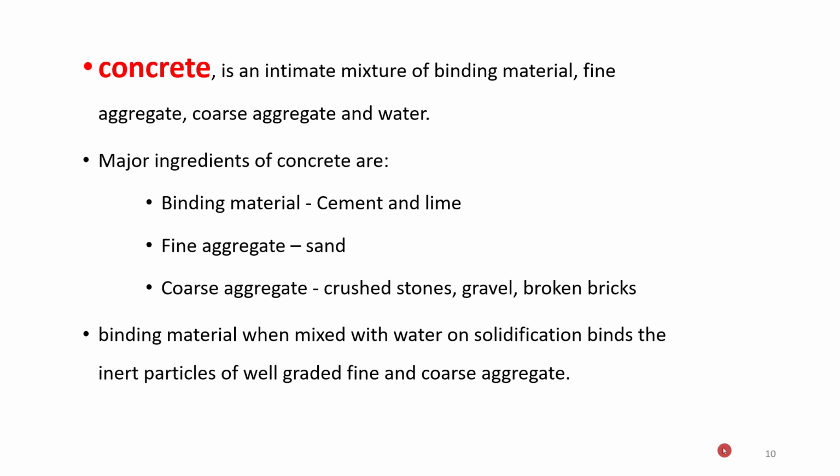When you come to the concrete, I'm explaining only the topics which I haven't taken in the class. I covered the major portions, and these are some additional topics in concrete. So you all know how to make a concrete. The concrete is basically the cement mortar plus an extra additive, the coarse aggregate or the metal. So when you mix the concrete, compared to the cement mortar, you will add the sand, add the cement, dry mix it, then add the metal, then again mix, then make a small hole, and pour the water into that, and you have a thorough mix.